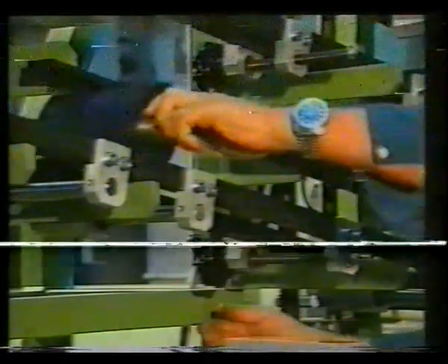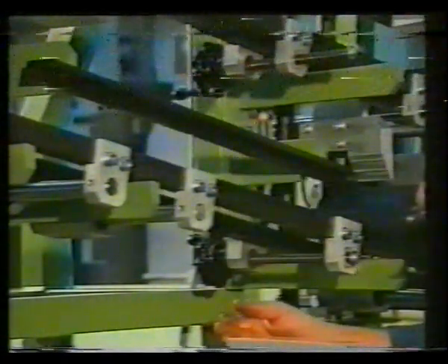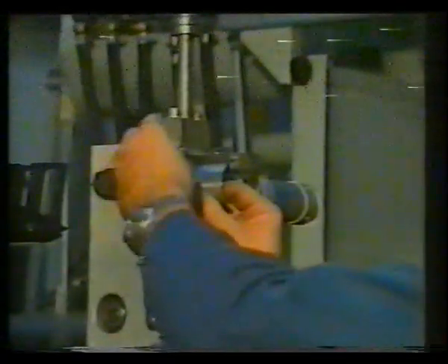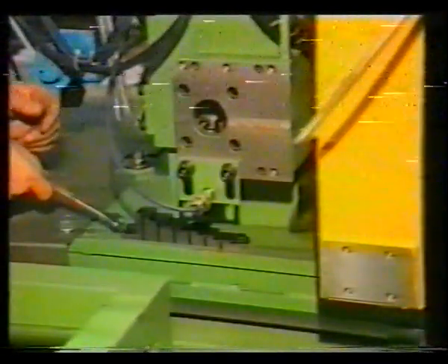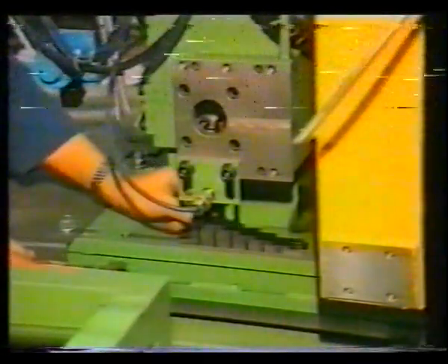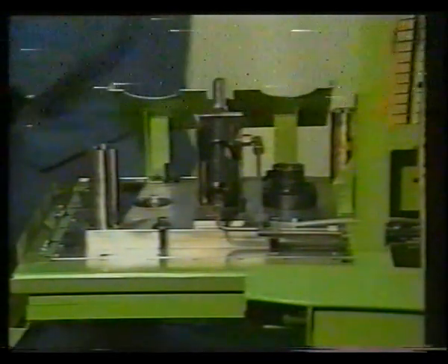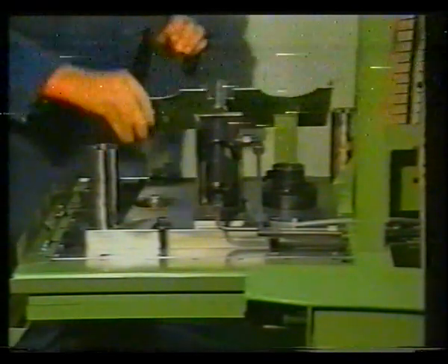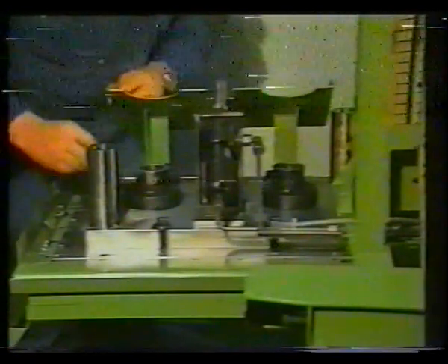Change the lamination stack stops. Adjust the feed track to the new stack height. Change the prism of the pick mat gripper tongue. Adjust the vertical height stop of the pick mat unit. Change the lower part of the trimming die. Change the top part of the trimming die.